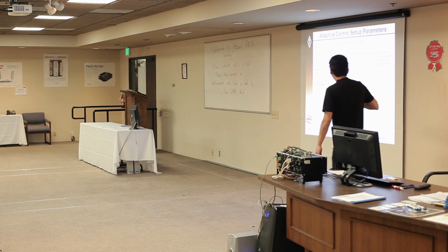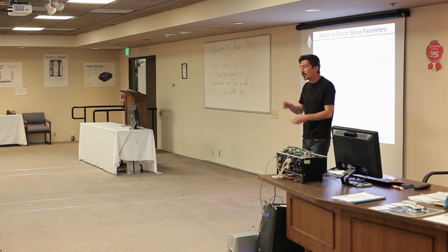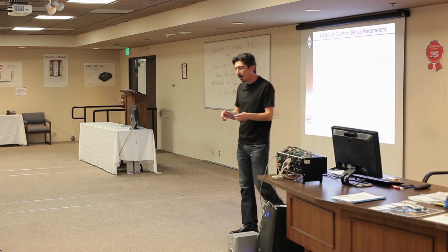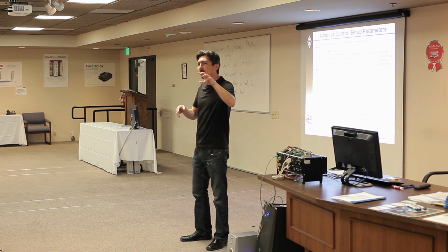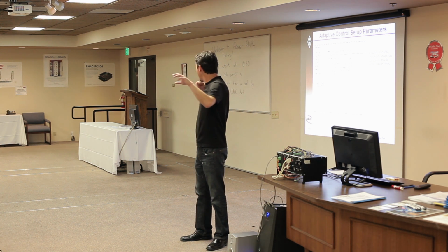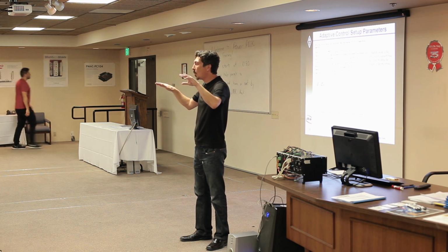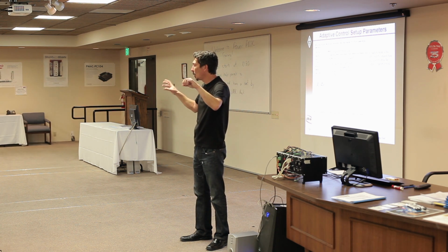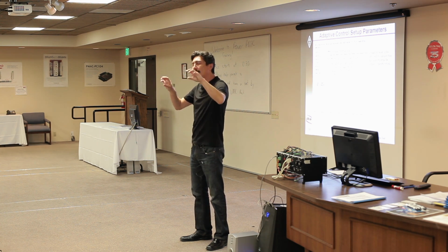And in this slide, we don't have it, but there's one more, a slight variation of this adaptive control law. One of our customers wanted something like this. When you have the maximum inertia, this adaptation will make sure that your bandwidth, no matter how your load changes, is going to stay the same with the same damping ratio. But they want something a little bit different.